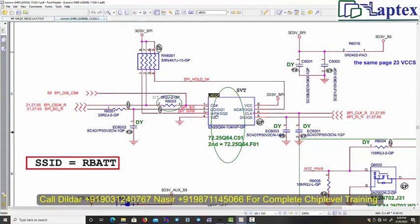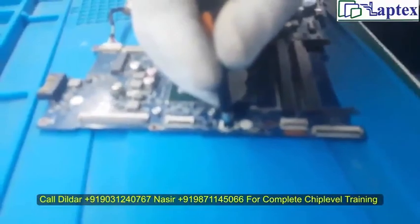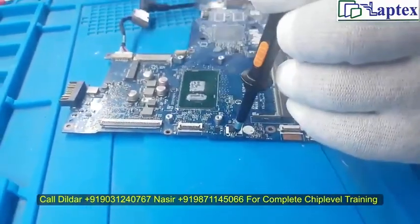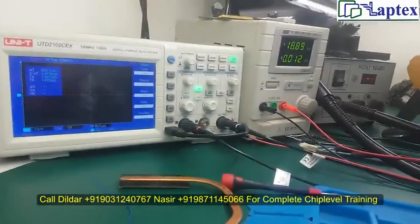So you have to be very careful while checking pin number 3. There must be 3.3 volt. You can also see here the 3.3 SPI supply is coming through this resistor, a 4 kilo ohm resistor, and you have to be very careful. You only have to check 3 volt. Let me show you what you get on this point. So pin number 3, 1, 2 and 3. After CS, these things you have to check. The sequence I am telling you.